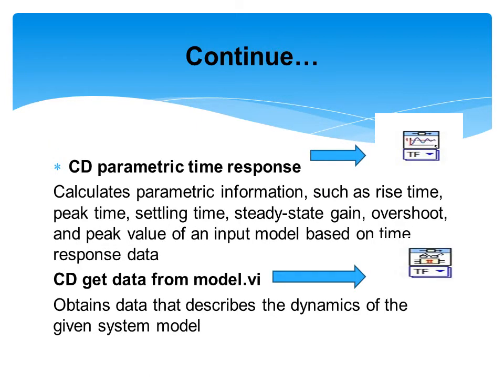And the next is the CD Parametric Time Response. In this icon you can calculate parametric information such as rise time, peak time, settling time and the overshoot. CD Get Data from Model.vi obtains the data that describe the dynamics of the given system model.